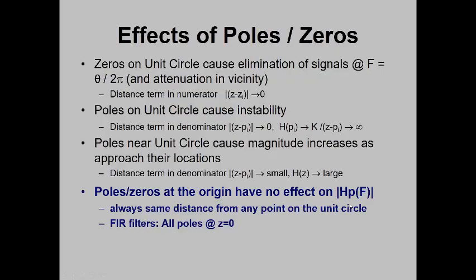Turns out an FIR filter, a non-recursive filter, must have all of its poles at z equals 0. If I violate that, the difference equation I recover from my pole-zero diagram will necessarily have some y of n minus something terms in it.